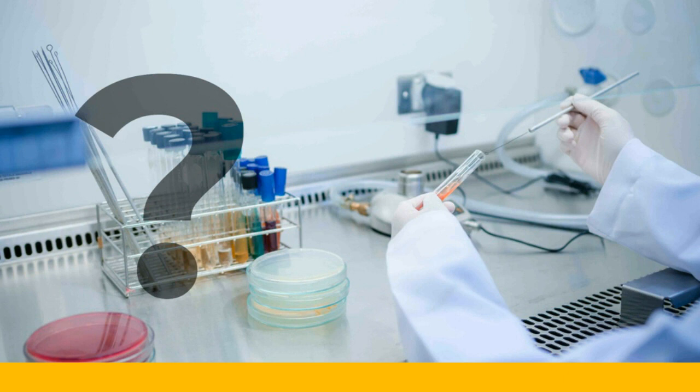Now, on the flip side, if you put a product that's not properly dried and cured into that can, we have seen other brands use this technology and have mold and mildew grow inside that can because they didn't properly have the moisture removed from the material. So, yes, I feel these are going to be some of your best options. Just ensure that you know what the water content is of that product going into that can to prevent that from happening. Absolutely. That was the other thing I was going to throw out there. Any sort of moisture containment, either in process or quality by design, or using some addition that is controlling that, will help you in the long run.